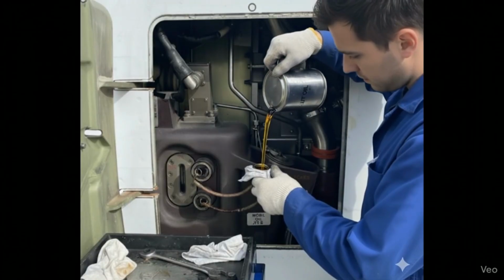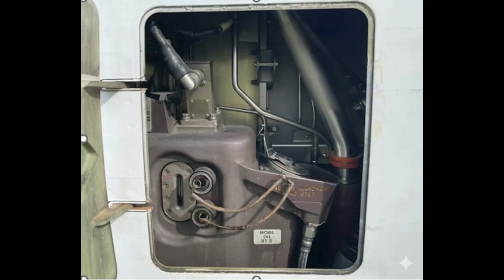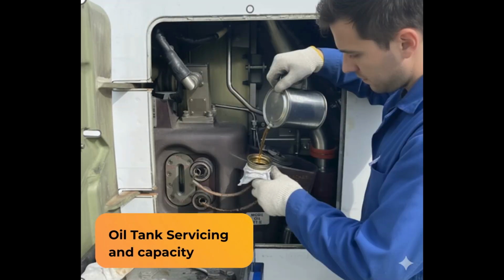Oil scupper and drain. During servicing, any oil spilled from the fill port is collected in a scupper connected to a drain line. This fluid is then discharged overboard via the drain. Pressure fill port. The system also allows for replenishment via the pressure fill port. This port is located on the front of the tank, to the right of the sight gauge, and features 2 connectors.